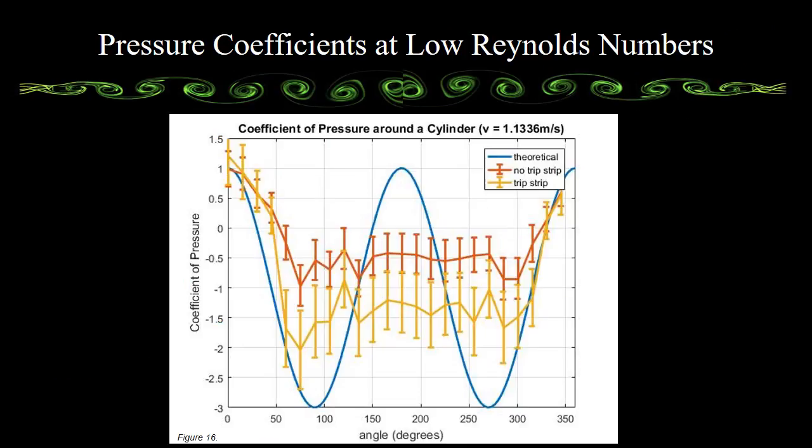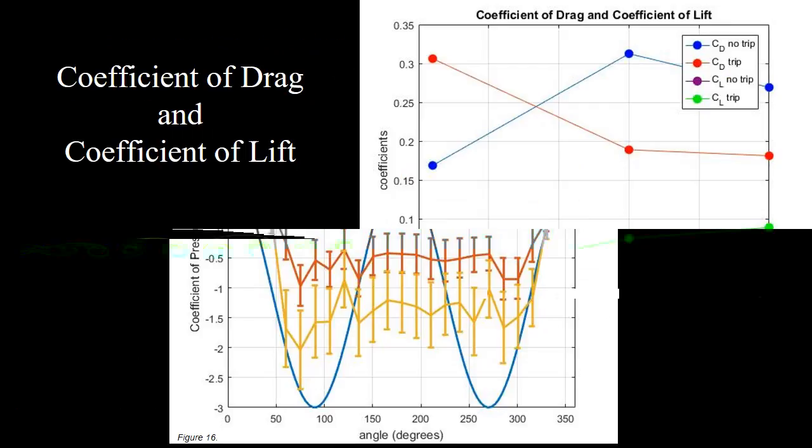For the laminar case, the pressure behind the cylinder has decreased, instead of increasing like the other two cases. The profile does appear to more closely follow the creeping flow approximation around the surface of the cylinder, leading to the assumption that the separation point has been delayed. However, the pressure behind the cylinder has decreased. The tripped pressure coefficients at this velocity more closely resemble those of the transitional profiles. It is possible in the low Reynolds number case that tripping the boundary layer caused the flow to become turbulent or transitional instead of laminar, resulting in the lower pressure behind the wake region.